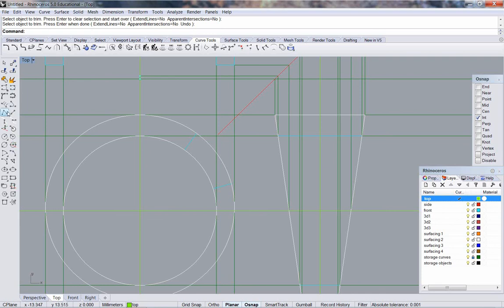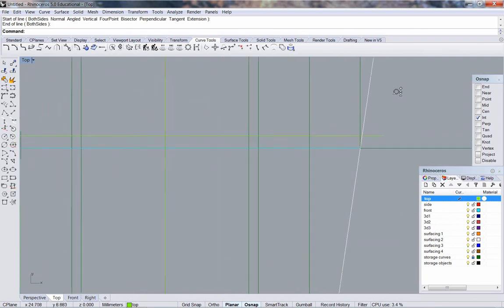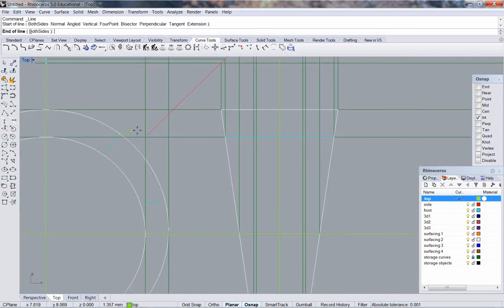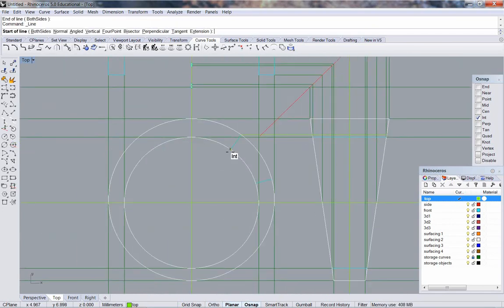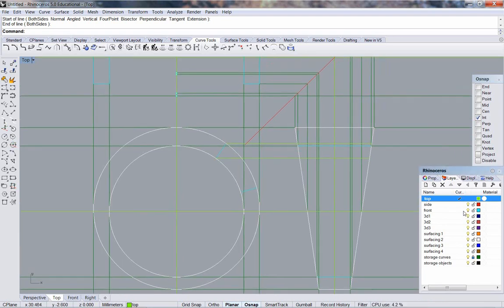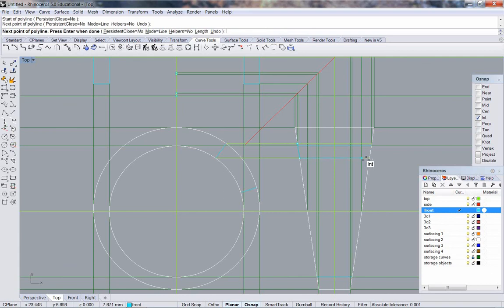Okay, construction line over for the top of the section till it reaches the edge of the ring, or goes slightly beyond. I took it beyond a little bit because once again I'm getting a lot of information here. There we go, that's right to the edge. And the bottom, right to the edge. And now I can draw that section in the side view. Once again, being affected by the taper as it runs its edge along it.